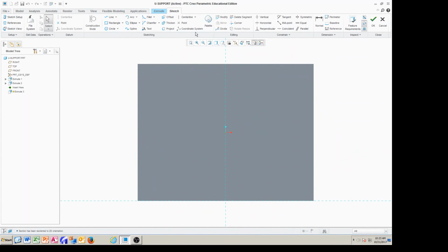surface. Again, we need to create a project line, so it will allow us to come up with a center line, which is going to be passing through the midpoint of this line here. So this way, if you want, you can just do the same thing. Go for this one, you don't need to place the projection line or project line. Just follow this, coincide the center line with the existing dash blue lines. Okay, all right, so you place it there.